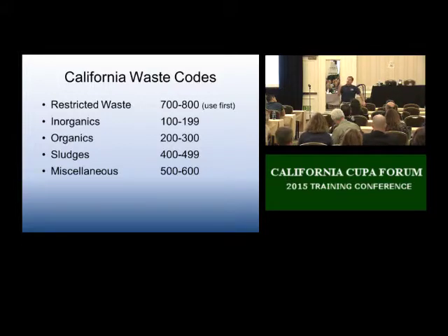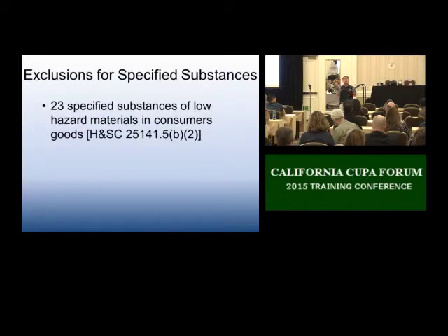Because they know that when you run the federal TCLP, when you digest it, you're only digesting the soluble matrix of the lead out of the dirt. Not all the lead dissolves when you run TCLP. Only the soluble lead dissolves. And then whatever dissolves, that's diluted 20 to 1. So when you run the total, the concentration you get for the total would have to be at least 20 times above the magnitude of the TCLP to possibly fail the TCLP.